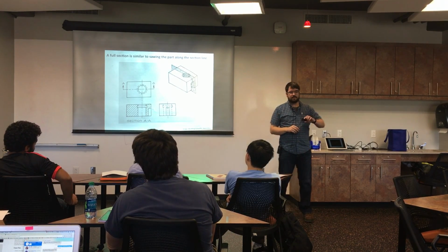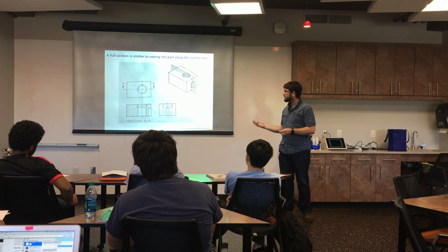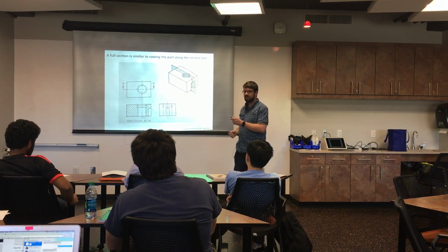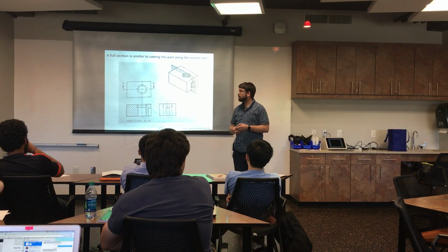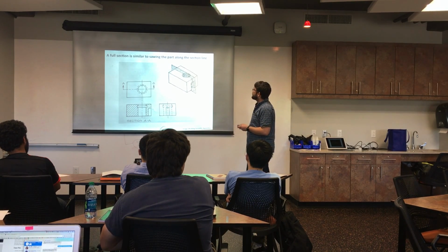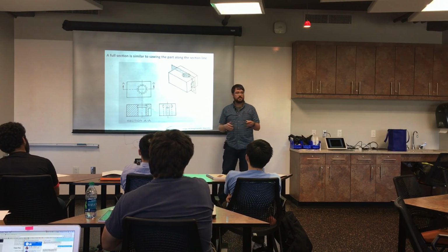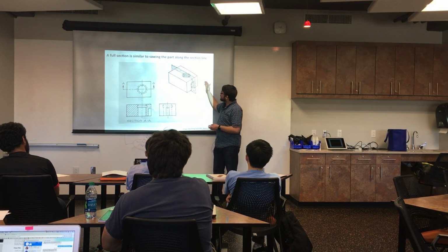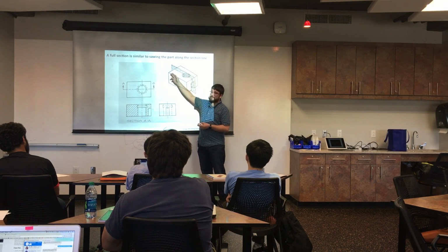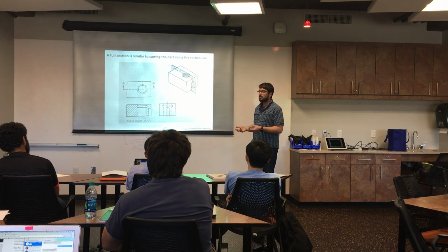When you have a lot of features that are inside the part, so holes or passageways, something that's really common in rock mechanics is we have fluid passageways in, say, end caps or in blocks that we're using to hold samples. You can show them with a section. So a section is actually kind of like a geologic section, right? We're going to pretend like we take the part, put it on a saw, and cut straight through it. Or if you had the water jet, I suppose you actually could do this. You would destroy your part. And then you're going to draw exactly what you see there.